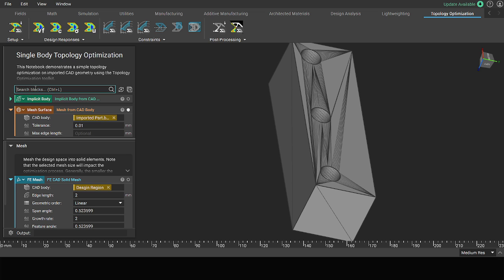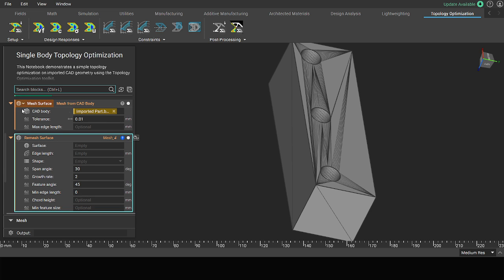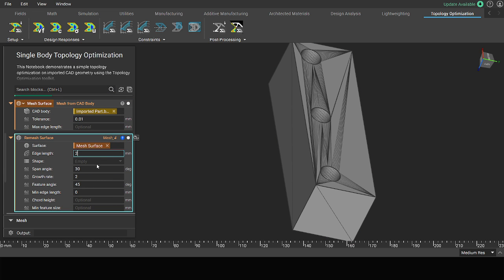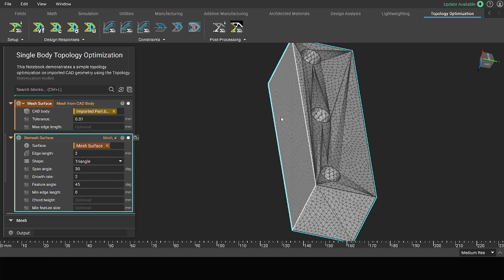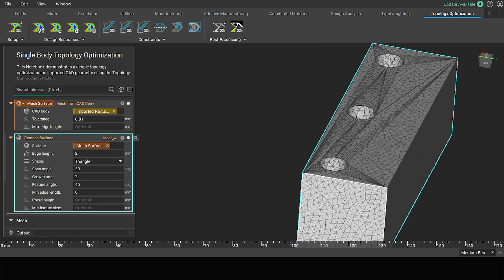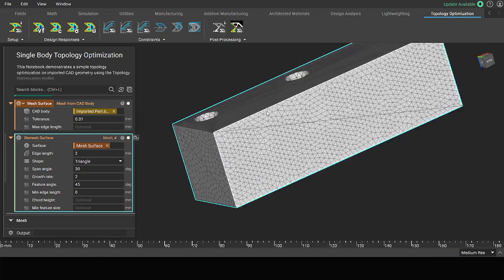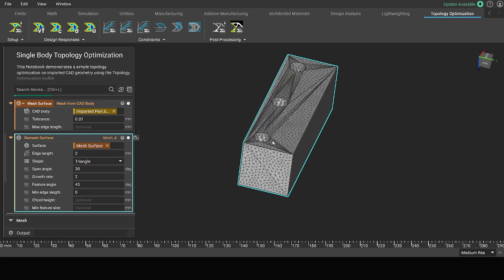And then I would mesh the surface. Now you see how there's kind of triangles, but they're not all the same. So I want to have those evened out. So I would remesh surface. And you're going to see, because it's a variable, I can drop and drag. I'm just going to give it some edge length. Triangle. You can see it's computing down here. Now look what it did. Now it made basically isosceles triangles. They're all equilateral or equal shaped. That's on the surface.